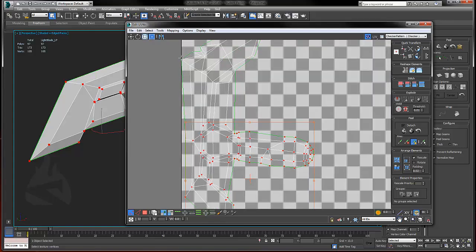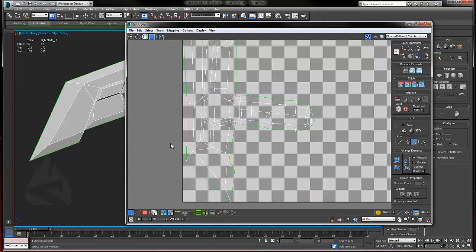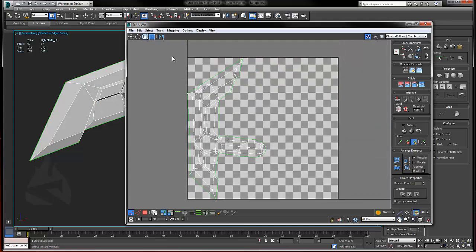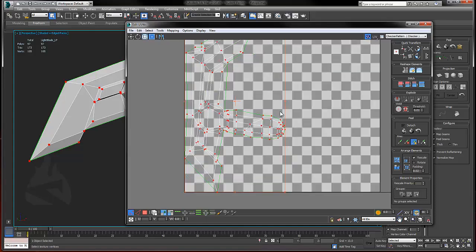Essentially, I want a nice straight line from this vert to that vert. And that's enough editing. I don't want to adjust it too much. But now I want to line this guy up so that edge is nice and flat. I'll grab these vertices and come over here and say align vertically. And so now they're kind of perfect.